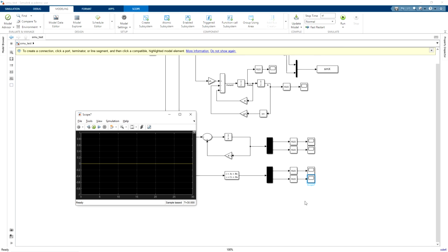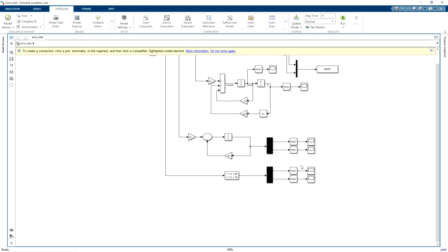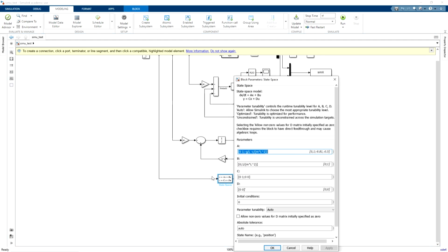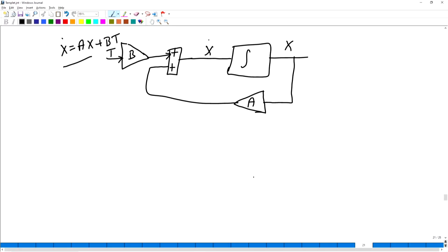So there is some issue in velocity here. Let us see what that is. All right. So what we did here was we have written C matrix as [1 0]. All right. So let us write that here. So y equals Cx plus Du. Anyhow D is 0. So this is Cx.